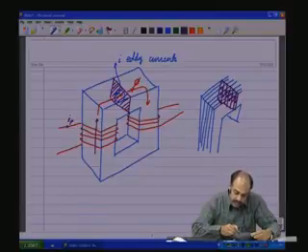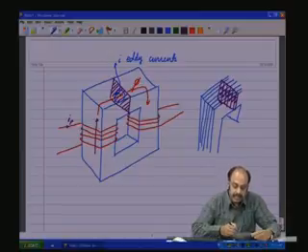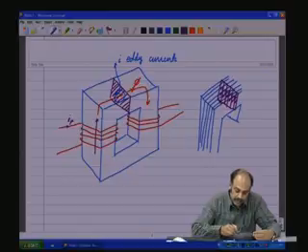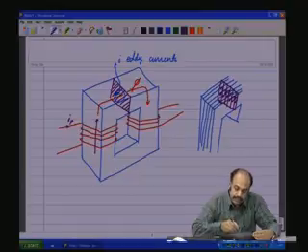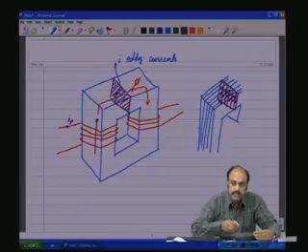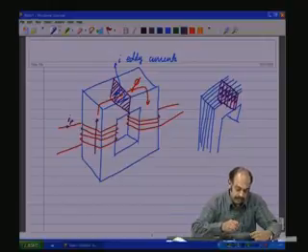Likewise, each of these current loops here, the eddy currents, will see a higher resistance due to the fact that laminations have been introduced, and as a result the induced current will be lesser because the induced voltage divided by the resistance is going to be lesser, and as a result the I square losses are going to be contained, much lesser than with a solid mass.